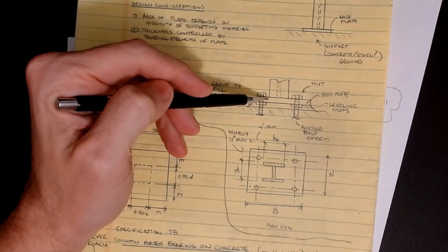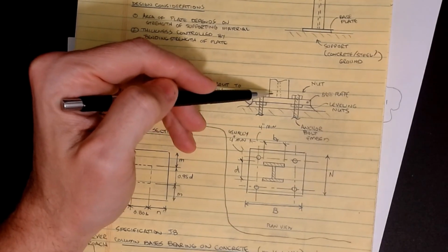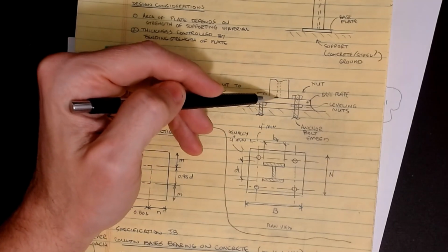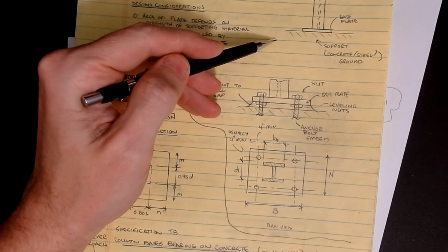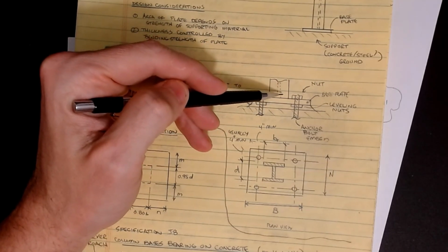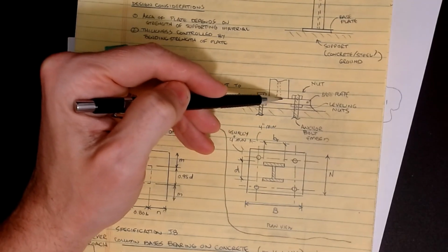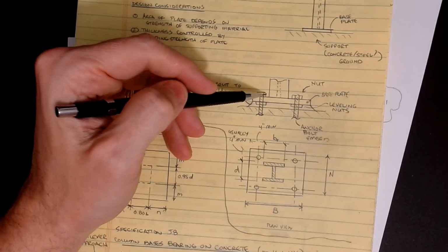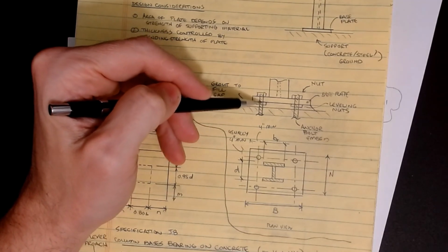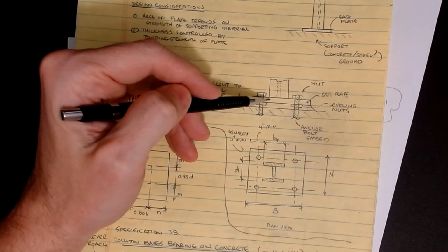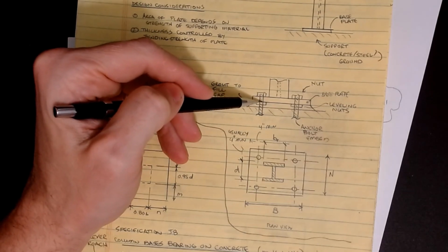One thing you have to be concerned about when you do that is that normally we picture a column being perfectly vertical, but in fabricating, it's possible that we don't quite get a square cut and this plate gets inclined. So a lot of times they will mount this plate so that it's not technically sitting on the surface.